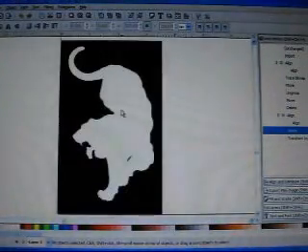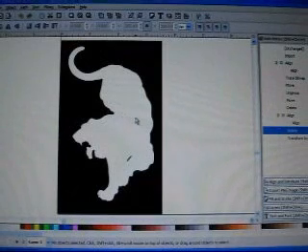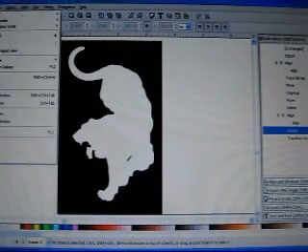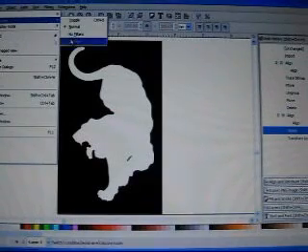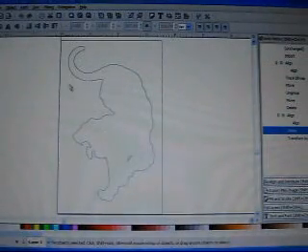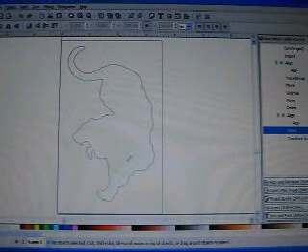So at this point we want to transform this to our exact dimensions what we need, which is 5.5 in height, and I'll zoom that back in for you so you can see it because I reduced the size quite considerably. This is a vector image and I'll show you how. You go to View, Display Mode, Outline. So that's the only information that we're going to save, and we're going to save this outline as a DXF file this time.